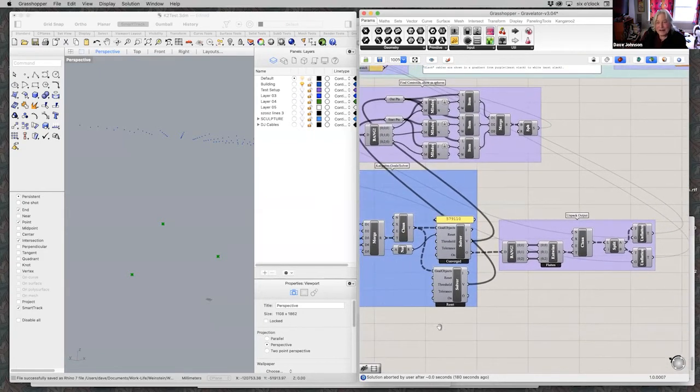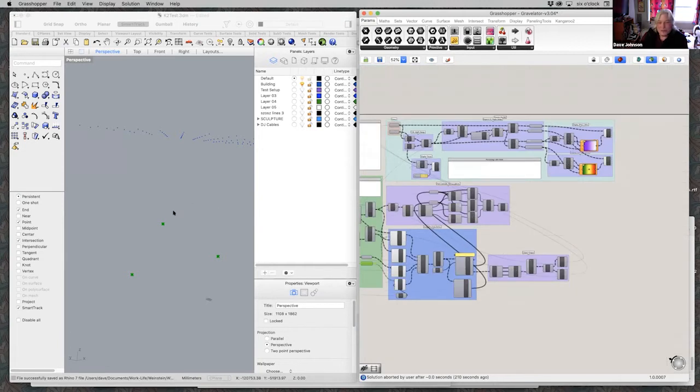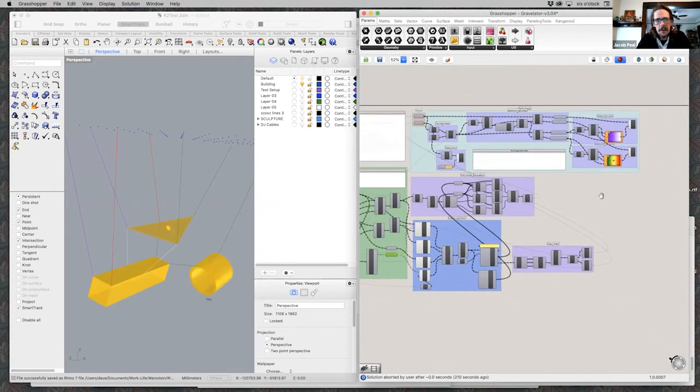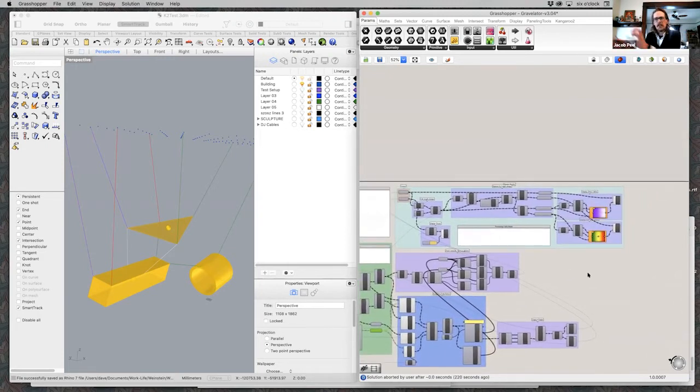And now I really had trouble unpacking the output sometimes, because Kangaroo does that thing where, if it finds 2 points, like 2 different cables have the same endpoint, it just uses one. It throws away the other one. So the tree structure that comes out at the end is not necessarily the same as what you put in. That was a real problem for me. There's a weird component called show, and that's a way of Grasshopper just passing something through unchanged that you can get on the other side.